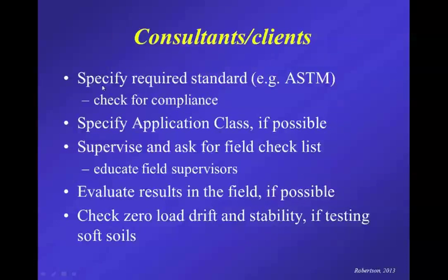So for consultants, specify the required standard. So if you're specifying CPT, specify which standard you want the operator to work under, and of course check for compliance. So make sure your field personnel are aware of the standards and they know what to look for. And then, if possible, specify an application class.